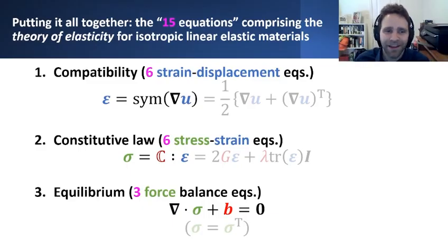that we might choose to pull it in. And that resulting stress-strain relationship, or that constitutive law, involved this relationship between the strain tensor, a rank 2 tensor, and the resulting stress tensor, also a rank 2 tensor, which required the definition of this rank 4 elasticity tensor, which made things quite a bit more complicated. But at the same time we could also reduce that down under these assumptions of linear elastic isotropic material behavior to come up with slightly simpler expressions, expressible in terms of only two unique elastic constants.